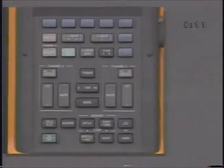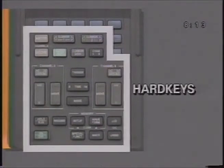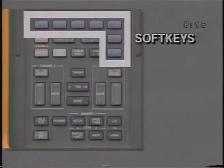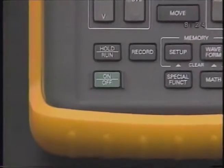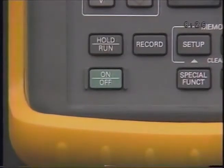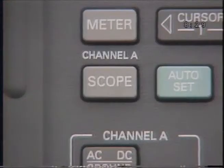There are 2 types of keys on the keypad: hard keys and soft keys. The hard keys are labeled. Their functions remain the same no matter what mode Scopemeter's in. For example, the on-off key always turns Scopemeter on or off. The scope key always sets it to the oscilloscope mode.